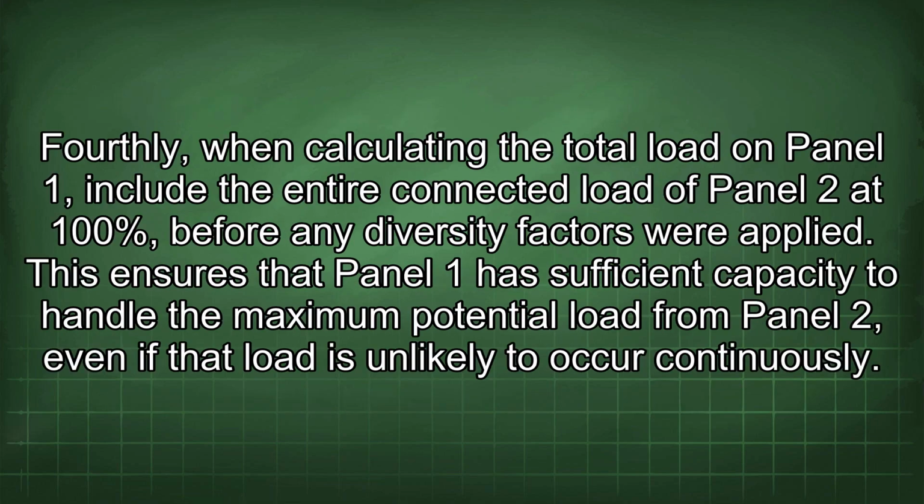Fourthly, when calculating the total load on panel 1, include the entire connected load of panel 2 at 100% before any diversity factors were applied. This ensures that panel 1 has sufficient capacity to handle the maximum potential load from panel 2, even if that load is unlikely to occur continuously.